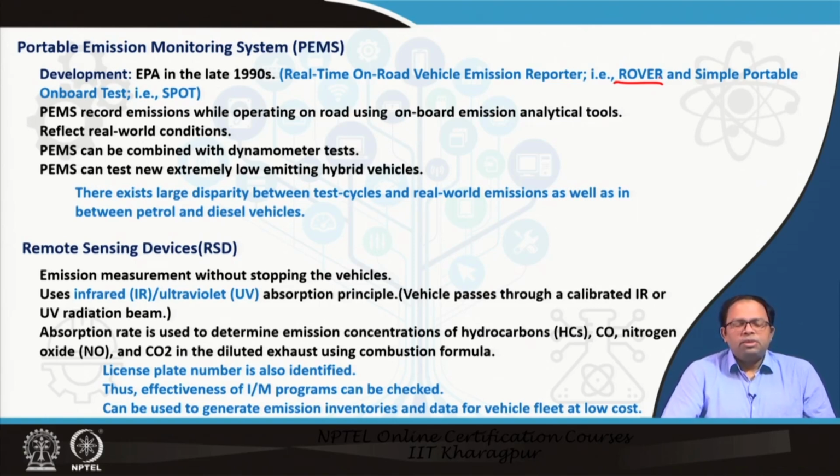PEMS records emissions while operating on road using onboard emission analytical tools. So that means it is a real world driving condition test. This is not happening in laboratory conditions, it happens in the real world and reflects real world conditions. This kind of test could be done independently or matched with a dynamometer test as well. This is a very good way of testing because it can also detect very low amounts of emission, particularly from hybrid vehicles and so on.